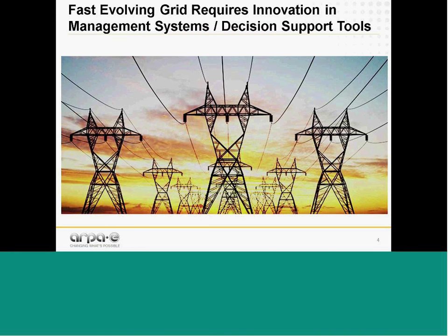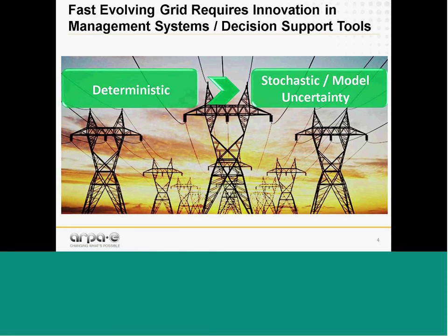There are a lot of issues out there today. Generally, our management systems and models are very much deterministic. We're transitioning from bulk energy resources being flexible and predictable to bulk energy resources like wind and solar that are not. This really calls for stochastic modeling, to understand how a wind resource should be treated differently than a conventional power plant. We don't do a good job of that today, and this is one change that would likely come.